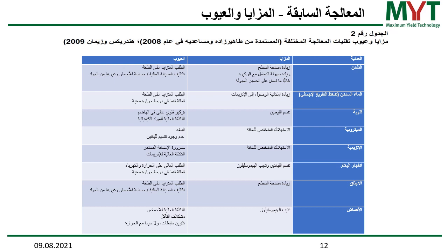Milling process increases the surface area, makes the substrate easy to handle. It very often also improves the fluidity in the digester. However, it's quite a high energy demand on such a process, and you have maintenance costs, in particular when you have sand and stones in the process. Then these might destroy quickly your sharp edges of the cutting devices.